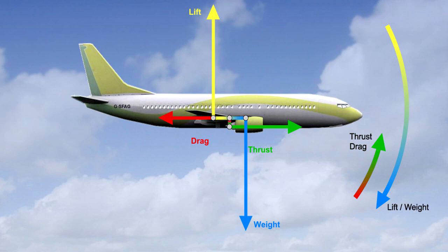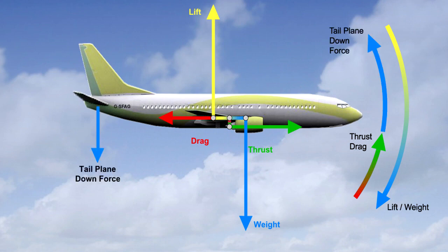In order to maintain level flight, we need somehow to generate an opposite moment which will balance the residual nose-down pitching tendency. This is achieved by the tailplane, or horizontal stabilizer, on the aeroplane's tail assembly. The horizontal stabilizer, or tailplane, must be set at an angle which will cause a nose-up pitching moment to balance the aeroplane, or, more commonly expressed, to trim the aeroplane. Notice that now the nose-up and nose-down pitching moments are in balance and level flight is possible.